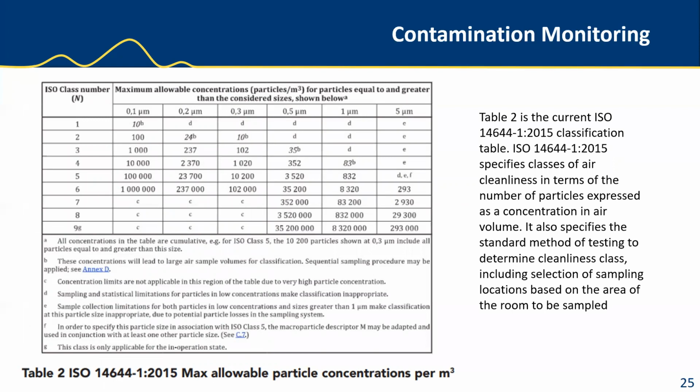So the facility department typically undertakes site monitoring activities in relation to cleanroom standards. ISO 14644 is the current cleanroom standard. This one came out in 2015. It's the current cleanroom standard, and it's followed worldwide in the cleanroom industry. Each room is classified based on the level of contamination observed in a cubic meter of air sampled.